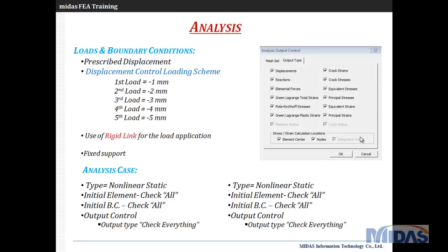Moving on, how the load and the boundary conditions can be applied. There are lots of ways to model and define the loading conditions when simulating this kind of situation. In this particular case, I will be defining the load as displacement control. It is the user's choice whether to apply the prescribed displacement at once with different incrementation, or to make stages so that the load is applied sequentially in increments like -1, -2, -3, -4.